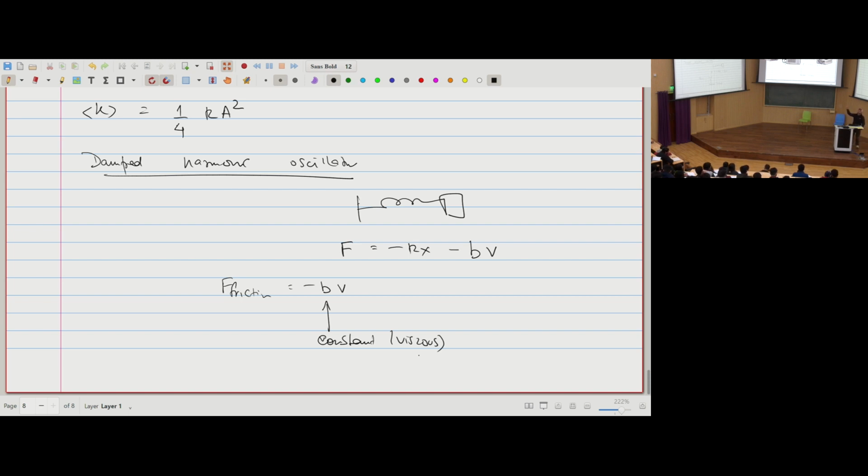So the mathematical model will be exactly the same, and so the output or the interpretations we have, or the analysis we will do for this mechanical system, will be equally valid for electrical oscillators as well, or other kinds of oscillators we experience in different domains of engineering. So this model is not simply applicable for mechanical systems. In electrical systems we have used a viscous friction or viscous resistance model, but the idea of viscosity comes from mechanical systems where you have air or a liquid.